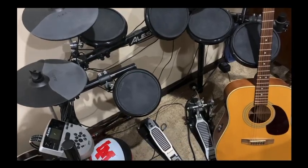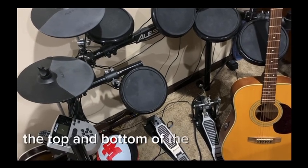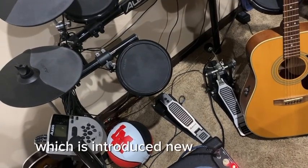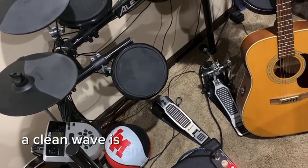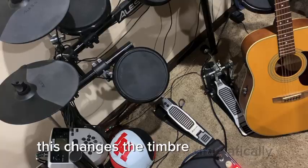When you turn up the gain, the amplifier boosts the signal until it reaches its voltage limits. Once it pushes past that limit, the top and bottom of the waveform get clipped flat. This is called nonlinear amplification, which introduces new frequencies, odd and even harmonics, which create the sound we know as distortion. A clean wave is smooth. A distorted wave is squared off and has more harmonic content. This changes the timbre dramatically.